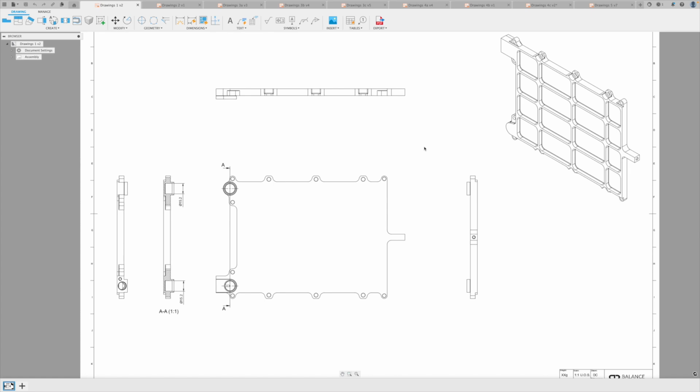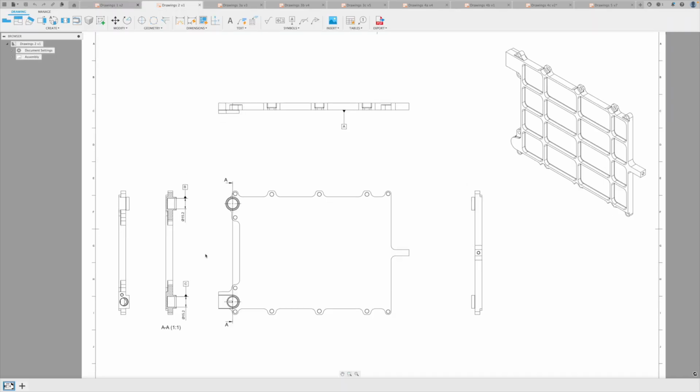Choosing holes that are far apart as locators means that any features between them will be well positioned when mounting the part. In this case, however, the holes around the edge of the part are clearance holes for the bolts, so they are not tightly tied up with tolerances. However, the holes in each of the two bosses appear to be more important and are likely to have tighter positional requirements, so we'll choose those as datums. You can see in this version of the drawing that we have chosen the large flat surface as our main datum and then the two holes as our remaining two datums.